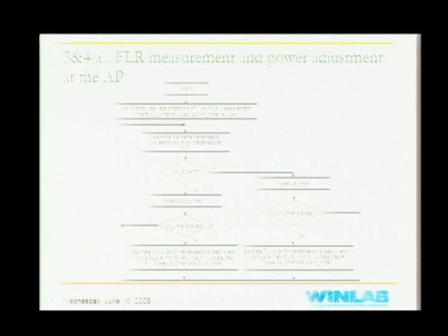So once it's greater than the threshold for a certain period of time, we increase the transmit power by P delta, and here P delta, PD, is 2 dBm. We just bump up the transmit power a bit more.